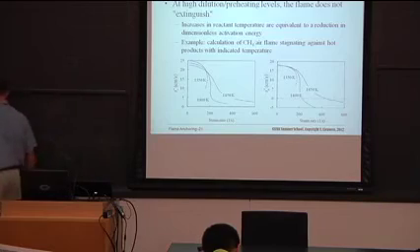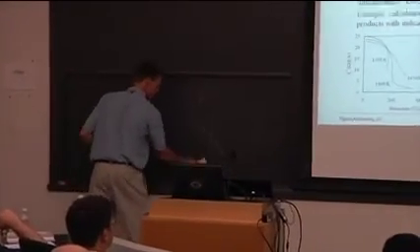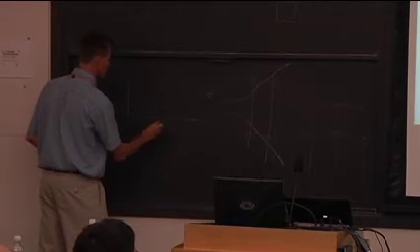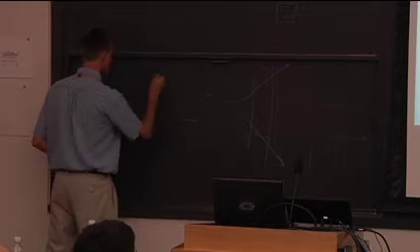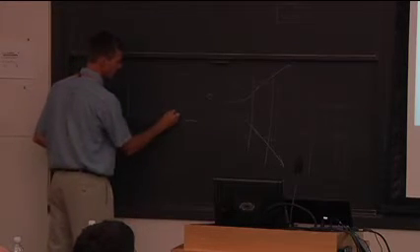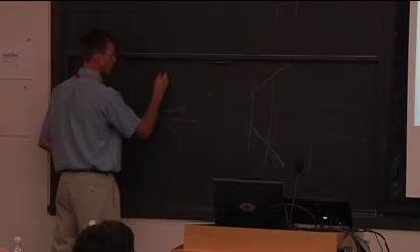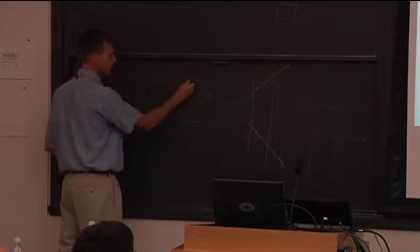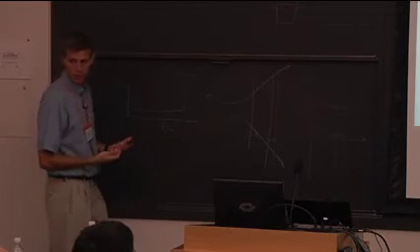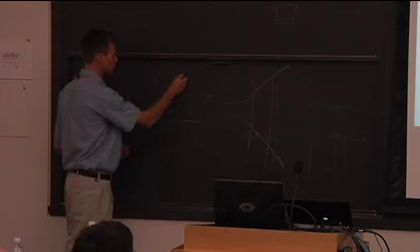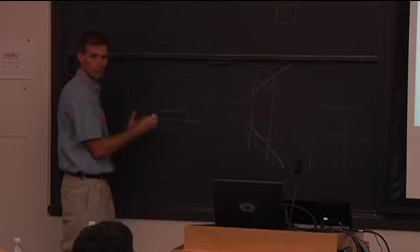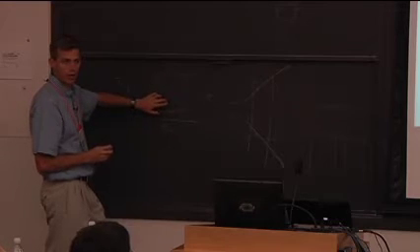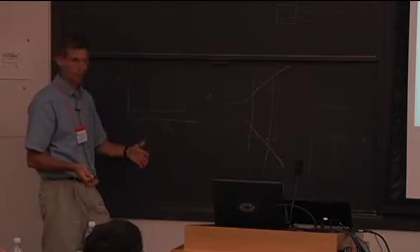I think you probably have this in your notes, if I remember from your combustion theory, for those of you who took it. If this is like a Damköhler number, you get a phenomenon that looks like this, where this is combustion temperature. You basically have a no reaction branch and a complete reaction branch. You have this hysteresis regime. This is extinction. This is ignition. And basically what's happening is we're stretching. When you stretch a flame, you're basically moving in this direction. Too much stretch, no flame. All right? Well, this means this occurs. You get S-curves because of high activation energy. Right? What's activation energy?